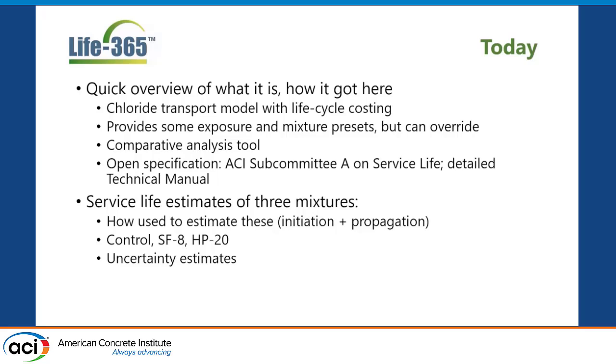I still consider it a comparative analysis tool. If you've got a structure, like a slab, and you've got multiple potential concretes you could use, which one is better than the other, with fairly good estimates of what initiation and propagation are. It doesn't mean that you're going to hit that number in 157 years, you're going to start to see rust, but it's a good lab-based estimate of what the corrosion is likely to be over the course of that structure.